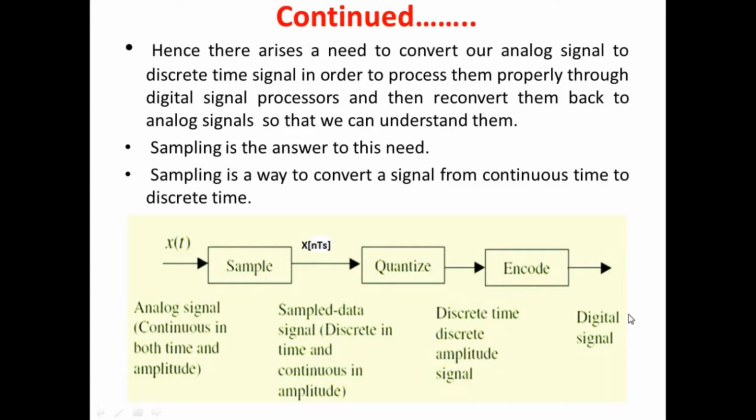At the receiver side we expect the message that the sender has sent, right? So in order to get the same original signal that the sender sent through a transmission medium, this process has to obey certain theorems and laws. For the sampling process it has to obey the sampling theorem, and if not, we cannot retrieve the original analog signal at the receiver side. At the sending side we have analog, but for a transmission medium we need a digital signal.